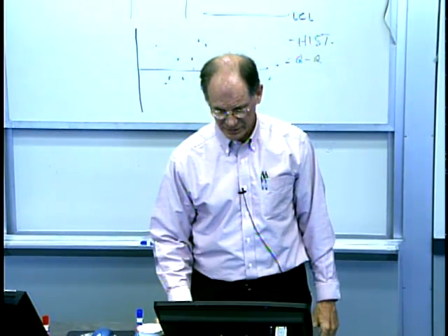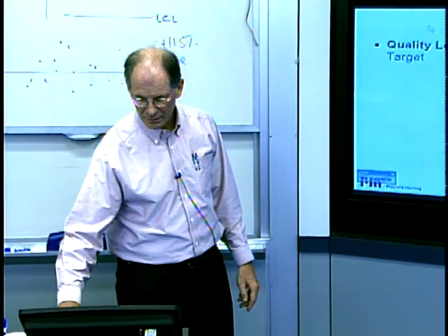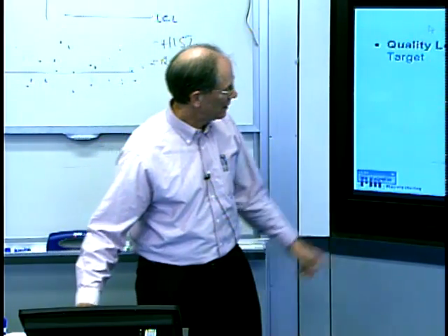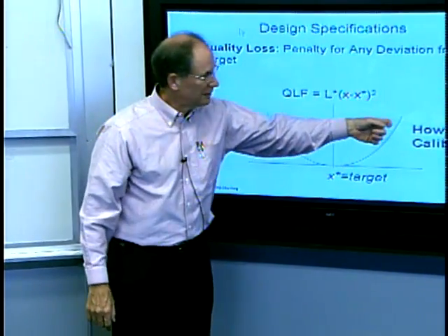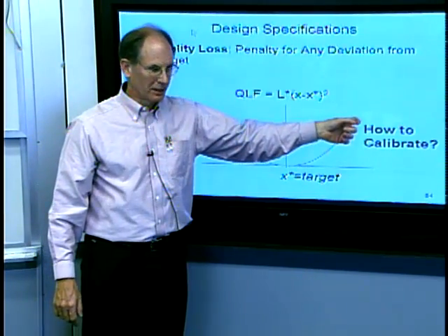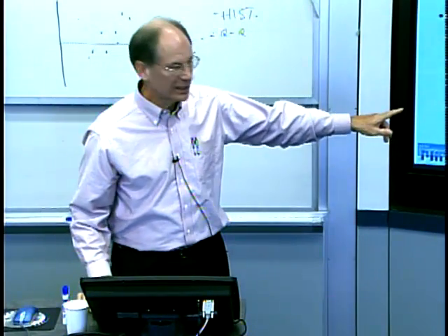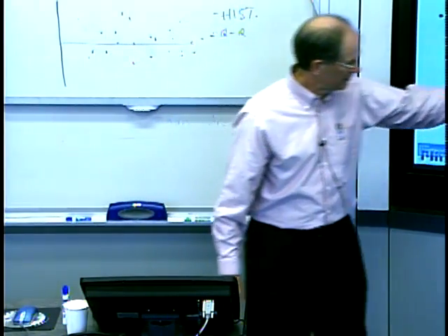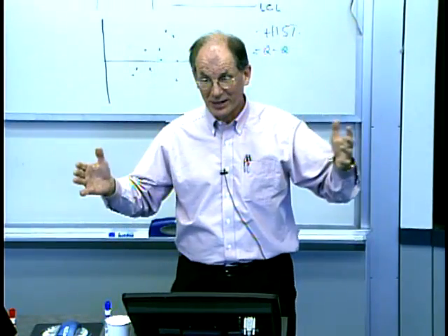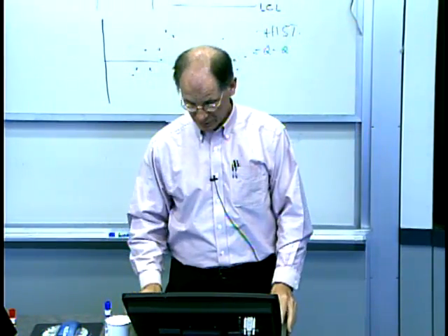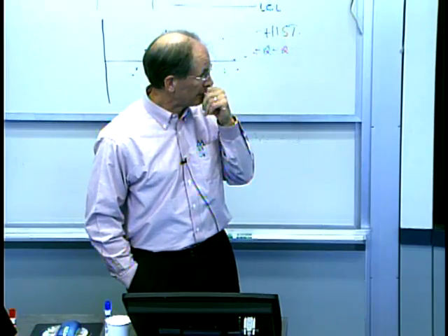And there's a simple way to calibrate this. If I actually have upper and lower specification limits here, I can ask, what's the cost of scrapping a part? Where this curve crosses that, you say, okay, that's my calibration constant. But again, there are some great case examples that show that if you work against quality loss, then once you combine parts into the whole thing, you actually end up with a much better overall quality. But for the moment, let's just look at the tolerances.